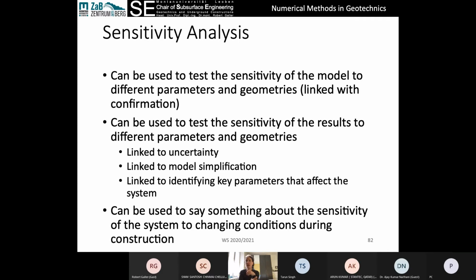We're also trying to say, if we know that we have variability, sometimes we're in a better quality rock mass. So for example, our granite is more weathered and less weathered in certain places, then maybe we have an upper bound condition with the unweathered granite and a lower bound condition with the weathered granite. And then we would do a sensitivity analysis. How much does that affect our deformations? How much does that affect the loads on our liner? What do we need to do for our sequencing? Do we need to do a split heading, for example? So then we use that